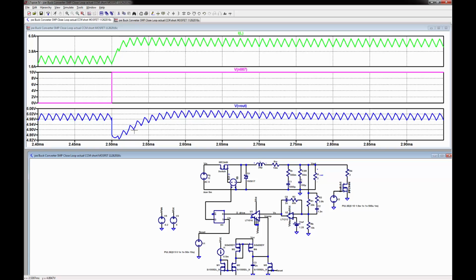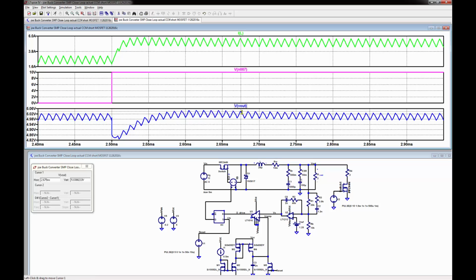But now, when does this got to play? When finally this starts to reach this steady state back to where this is again, finally we're going to see the slew rate and error amp start to meet where this error amp starts to take over, and it's the pulse width modulation again. So if you look at the output voltage in here, and you take an average somewhere in here, you can see that's about 5.05 volts. And if you take an average over here, that's about 4.99. The difference is your load regulation.